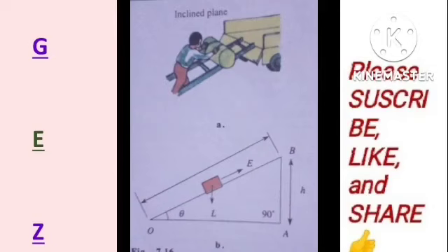So the velocity ratio and the inclined plane are related to the trigonometric properties of that shape, which is a triangle. Friction along the plane also affects the efficiency, and the mechanical advantage will be less than the velocity ratio of an inclined plane.